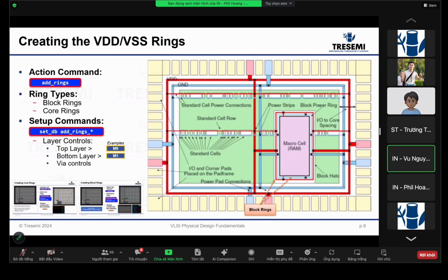You have the IO lower than the VDD core in some cases. There's also another type of IO called LVDS, which stands for low voltage differential signaling. It's basically a pair of IOs, and it switches at very low voltage, between 0 to 0.3 volt. But the supply to the pad is actually at a higher voltage, typically 1.8 volt.